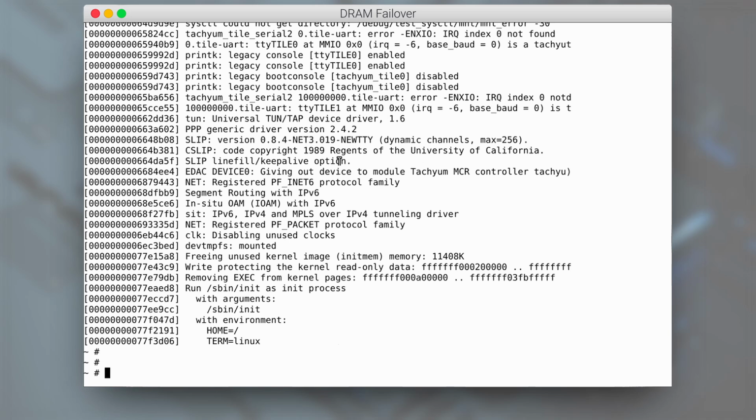Today's large, highly scalable data centers typically have thousands of processor cores with potentially millions of memory dies and require high availability and resiliency. Prodigy's advanced DRAM failover feature ensures the high availability that is critical for business continuity. In order to support this capability, we have several ECC options built into our system that we can invoke as needed, including monitoring logic in our DRAM interface so that we know when one of our dies has failed, with all logic built into the Prodigy device.